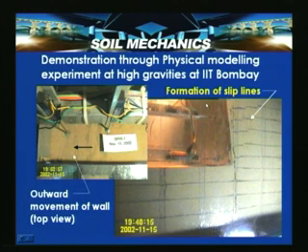These are shown just to see how demonstration experiments can be carried out and also to understand the concepts we discussed just now, like active and passive states. When the wall is smooth and the backfill surface is horizontal, two states are possible: one is the active state and another is the passive state. The passive state occurs when the wall moves towards the soil, and the active state occurs when the wall moves away from the soil.